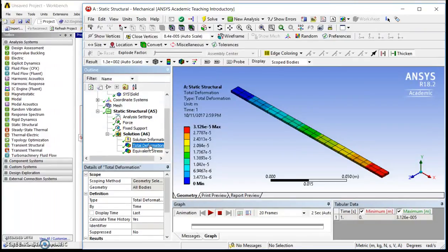Okay. So there is one more step here. You might feel inclined to stop, knowing that we've set up the geometry, meshed the system, solved the problem, and the answer agrees with the hand calculation. But there is one final thing that you want to do when you run a finite element simulation, and that is to reduce the mesh size and rerun the simulation.